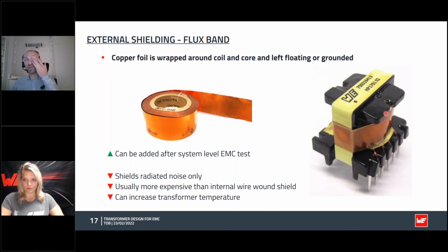You could wind a transformer without a bobbin as well, but it would be a lot more messy and not so pretty and very difficult to assemble on a PCB. The bobbin already provides a fixed footprint where the pins are, so we know what size the transformer will be, and also all the structure for how to fit the wires in internally. So I guess that's really what a bobbin is.